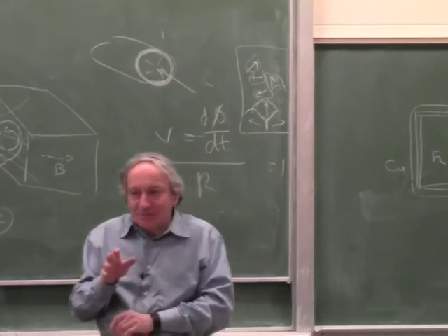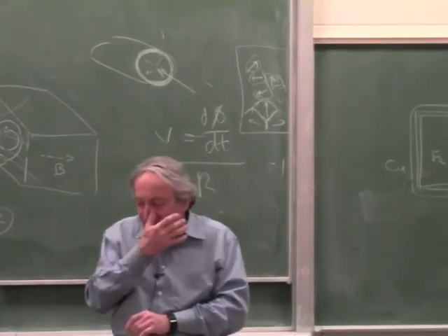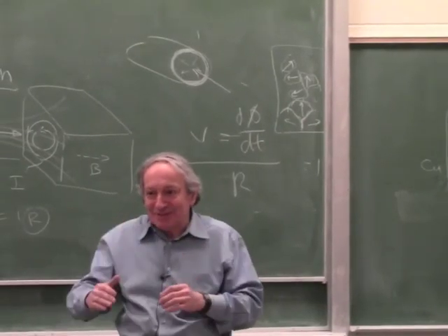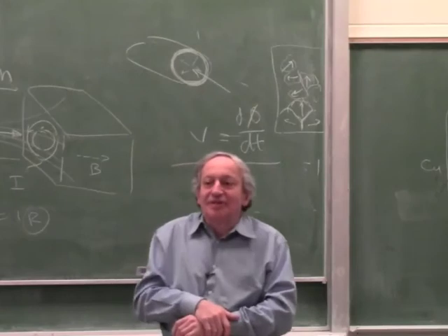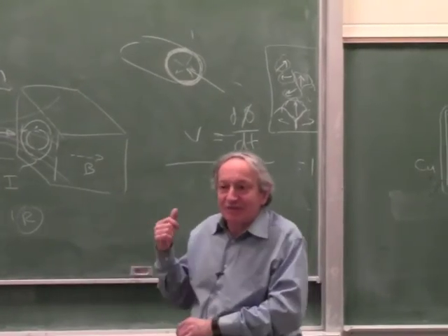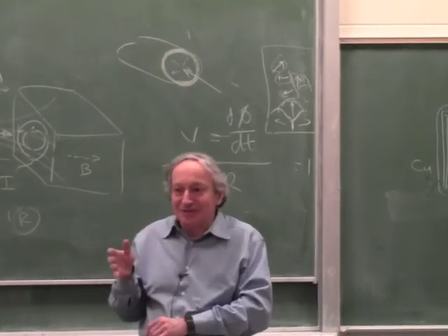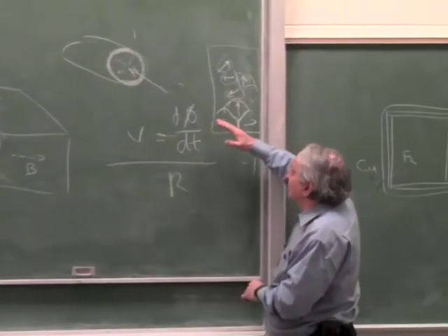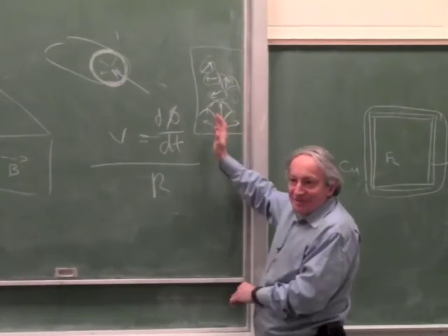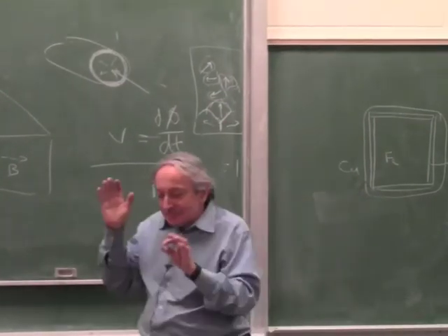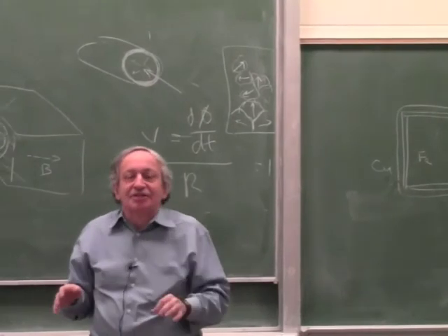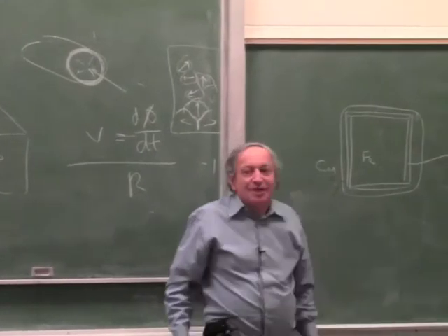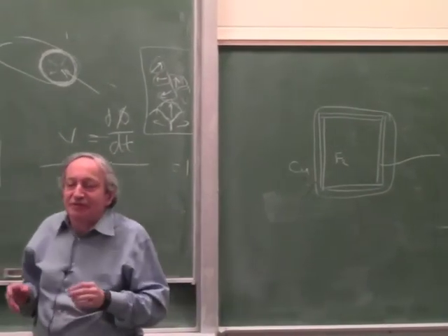It's actually not a simple effect. There's a Barkhausen effect, which is a jumping of the domains. There's a whole bunch of effects which take place. You can read up on it. But the interesting thing is that all these effects are visible. You don't need fancy labs to see it all. The Barkhausen effect is the effect that they don't move smoothly, they jump. So the bottom line is that shielding is not such a simple story. Sometimes you have to build a special box with two metals, the right metals, if you're dealing with very low signals.